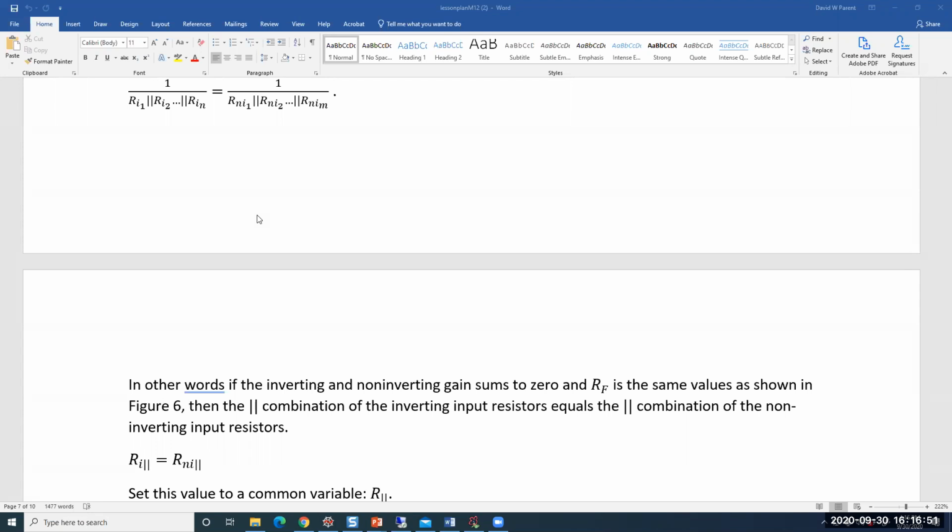What if I was trying to find an RA with a particular gain, but that RA was below 1K? For other reasons, resistances in these circuits below 1K isn't a good idea. So I might have just done it wrong.